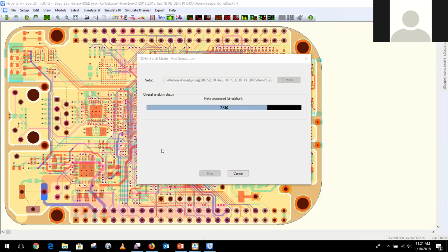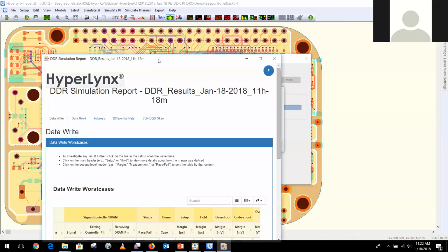and that help you define your next architecture, select your connector, and select your fab house, because you are checking the stack-up. You're playing around with stack-up values, and you can talk to your fab house and say, hey, can you do this stack-up or that stack-up? If the answer is yes, great. If the answer is no, well, they can't do what you want. So there are a lot of benefits to doing pre-layout, not just post-layout. Once everything is done, you can't really change anything. So it completed.